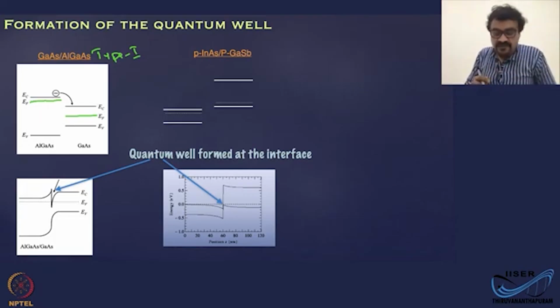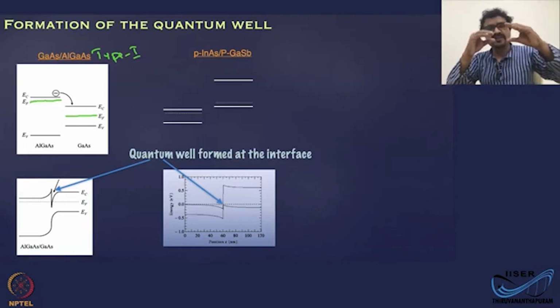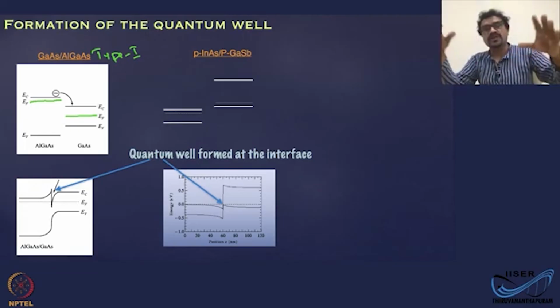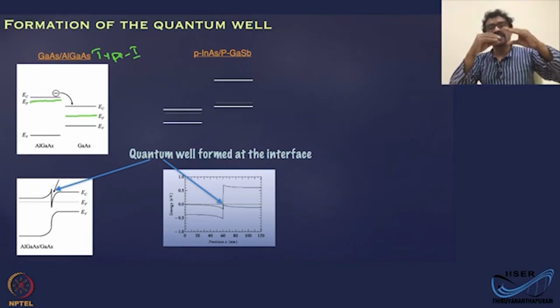And of course, when you do the process, you had this structure initially. Now when you align the vacuum level, you get something like this. That's how you define type 1, type 2, and type 3, how they are displaced when aligned from the vacuum level. This is type 1, and that is what we have for gallium arsenide.